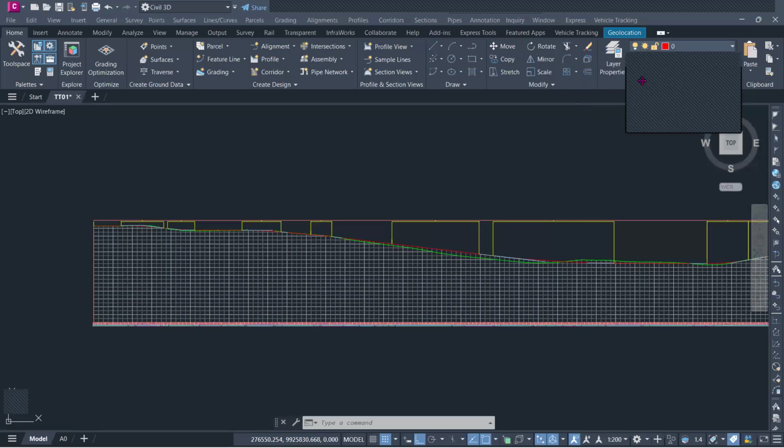Okay, thank you. So we found that even some sections that we had already designed for minimal cut, after opening up the area, we found what we call lateritic soils. It's a kind of soil that is more plastic, a bit rocky, a mix of rock and soil. When you move with the excavator, it's crushing the rocks to ash at that point. So it was a big surprise that really affected the project earthworks.